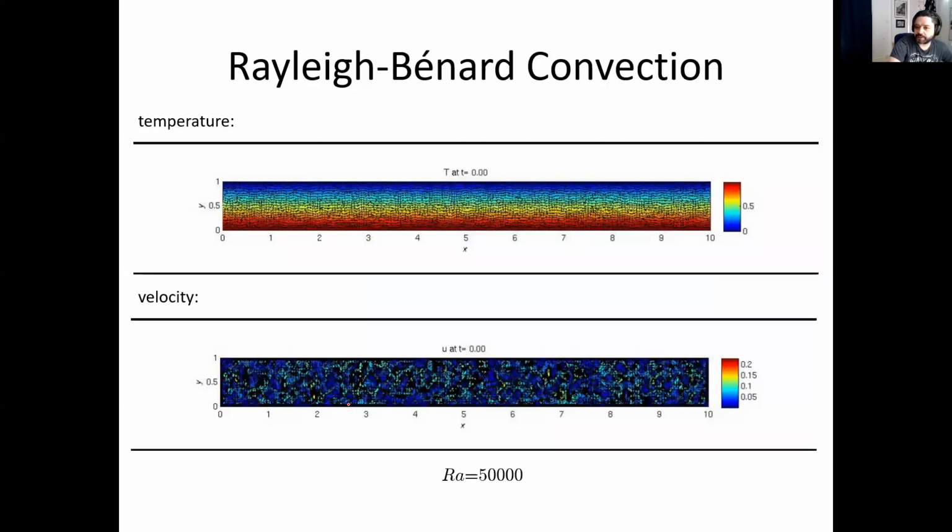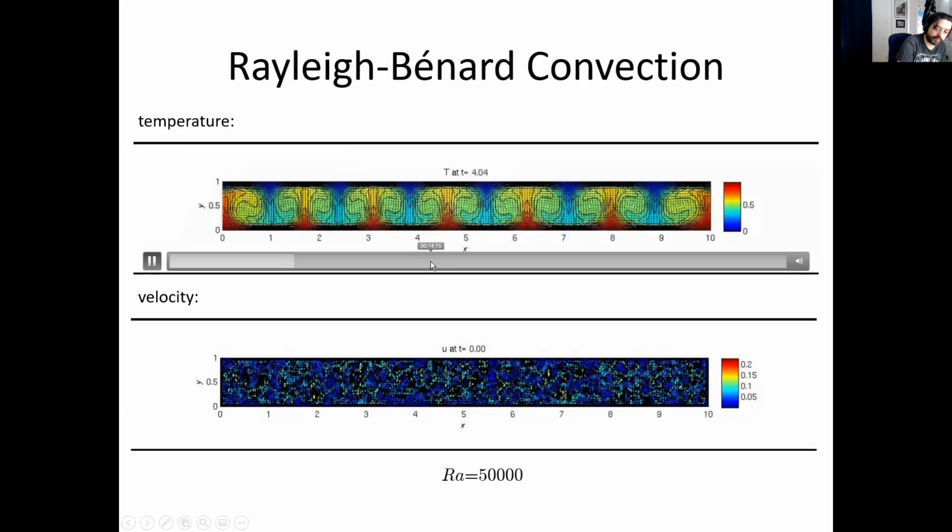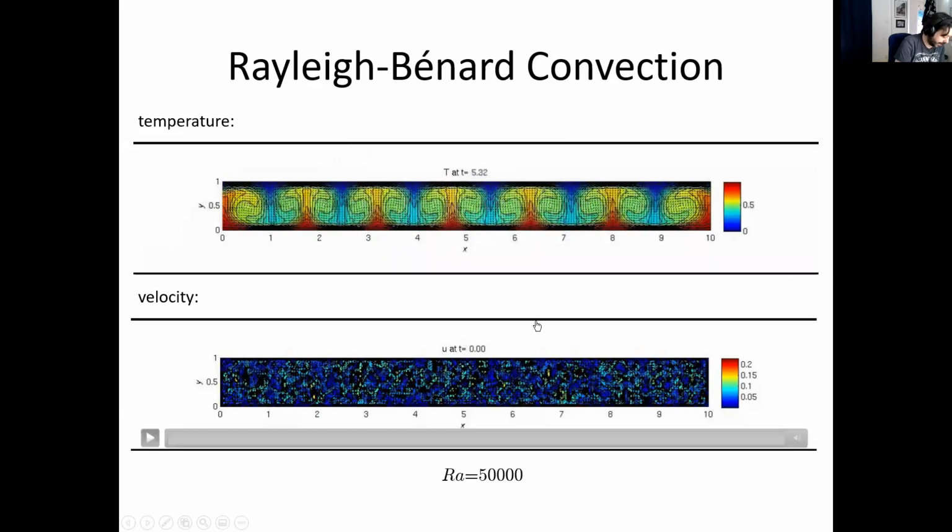Now the question is, what happens if we start to increase the Rayleigh number, which, as we said earlier, would be very similar to the Reynolds number by analogy. It means that you have less viscosity, more convection. Do that. You see, it also happens very quickly, but the shape of these convection cells has changed, and they look like this.